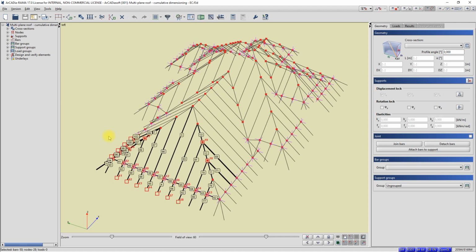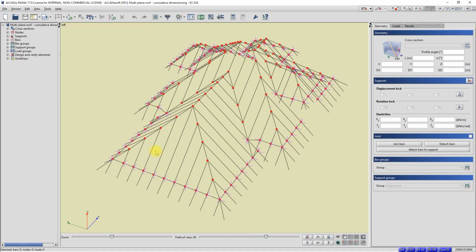Now I want to deselect several objects. I press the Control plus Shift key. I indicate the first corner point of the window. I move the mouse cursor to the left and specify the area of the window. I let go of the left mouse button. With the help of the window, we removed from the selection objects that were wholly or only partially in the window. I press Escape and uncheck all selected elements.